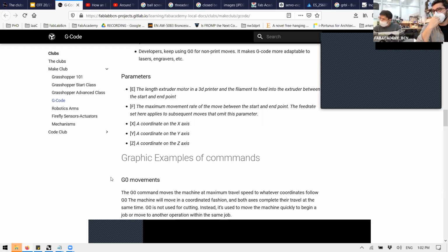In general you always use post processors. For 3D printers, Cura is a post processor. RhinoCam is a post processor for CNCs. The Rhino plugin of Cut Studio for the vinyl cutter is a post processor for vinyl cutters. But you are able to actually do the same. So for example, a case study application: at home, I have a 3D printer, and I do a lot of experimental stuff. When you move your machine with the joystick, like pressing plus X to move it, what you are doing is G91, set relative coordinates.